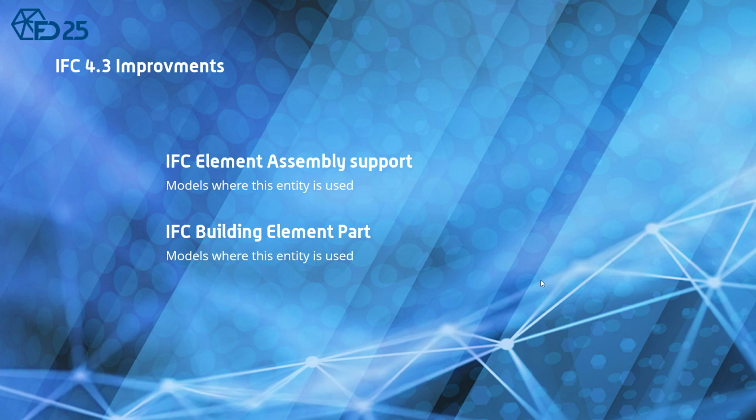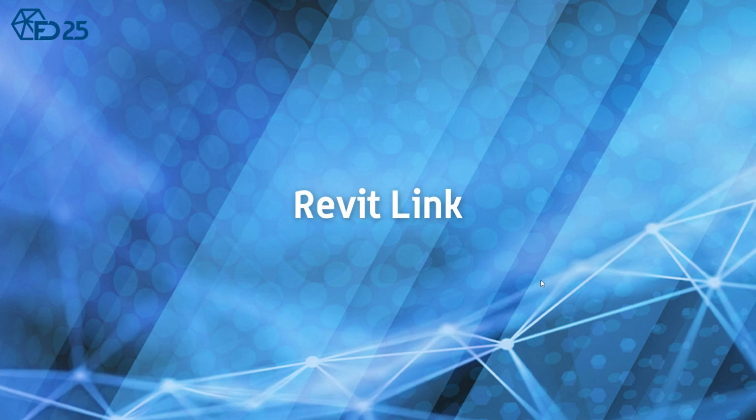Other improvements we have done: we now have support for IFC element assembly. Some software will put those IFC beams and slabs inside of an assembly, so now that is supported. And IFC building element part is also now supported, so we can import even more different types of models. Then a few words about the Revit link, which has been dead for a few years, because Revit redid the whole infrastructure of how they transfer the data.